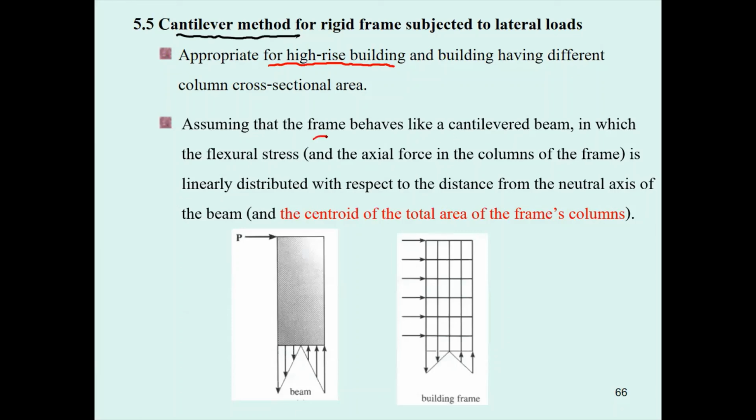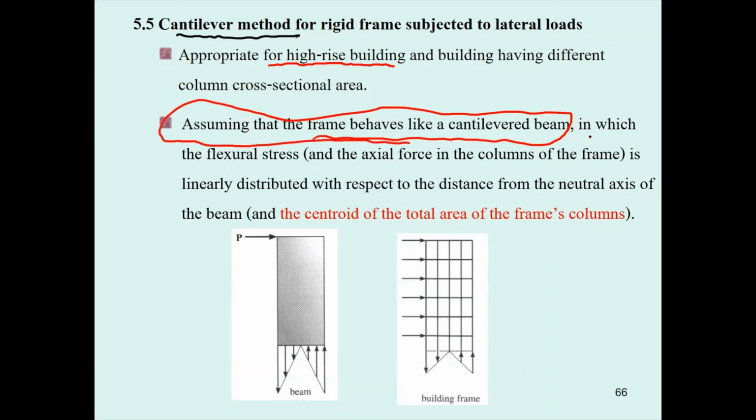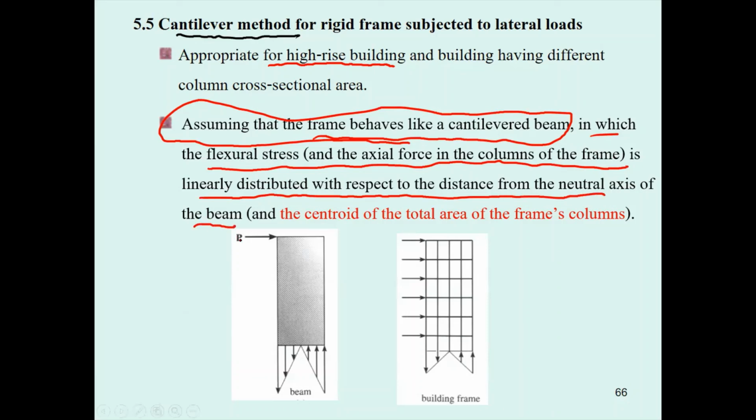The assumption of this is based on the cantilever beam, in which the flexural stress of the beam is linearly distributed with respect to the distance from the neutral axis of the beam. In this one, we use the centroid of the area of the columns in the frame as the neutral axis.